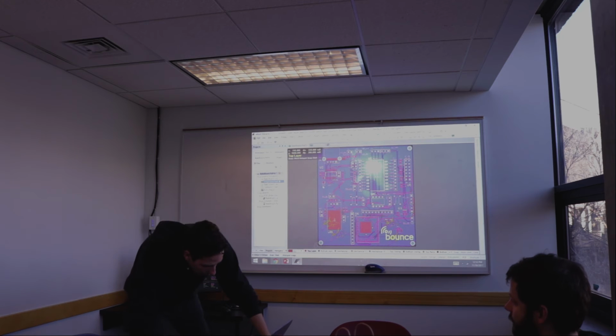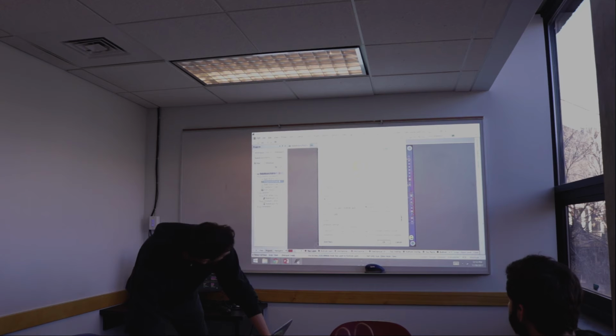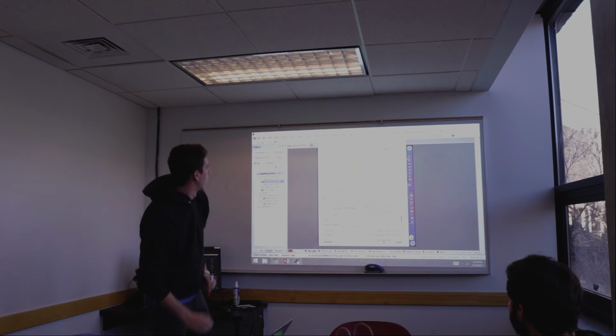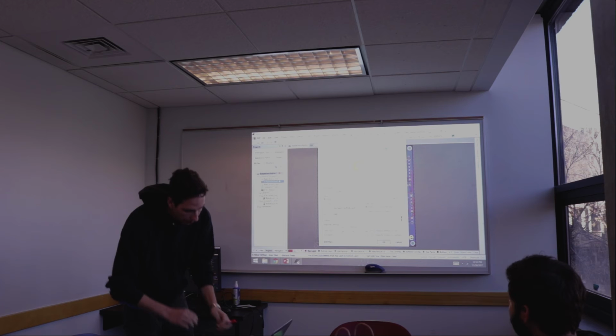Which is what for our case? 13 mils or 15? Yeah, I think 15 mil. Let's see, pull it up. So hole size 15 mils, diameter 28 mils. That'll be huge. That way we don't have to change all the vias on the backside. Yeah.